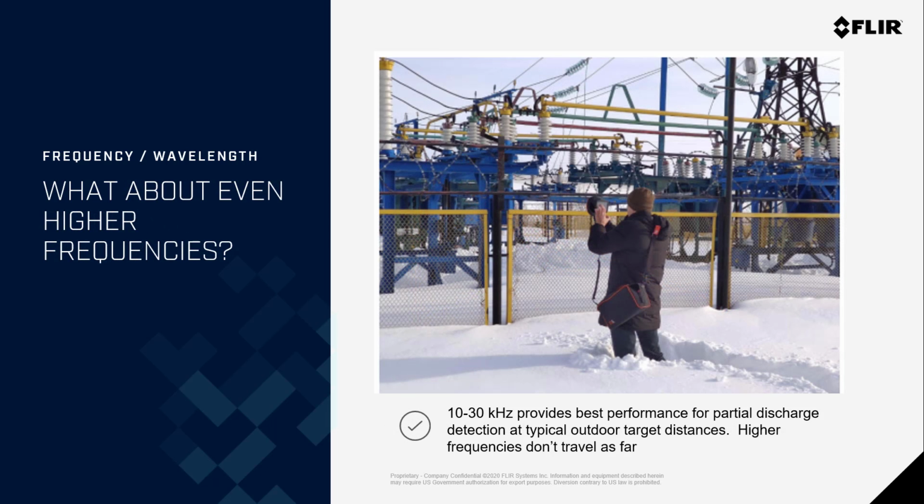Something that's important to know about sound waves is that the higher the frequency of a sound, the less distance it will travel, right? It's simple science. We found the distances needed to image partial discharge, for example, in outdoor electrical equipment, the best performance is between 10 and 30 kilohertz. Here we're showing a typical inspection of outdoor high voltage equipment where you really don't want to get too close to the equipment for some pretty obvious reasons.